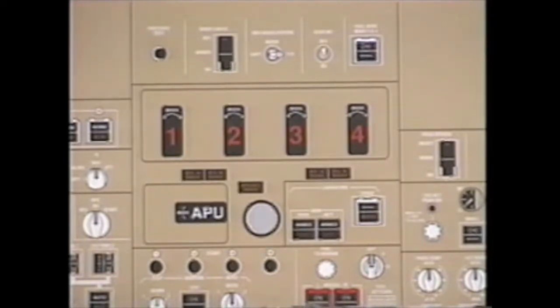This remote shutdown panel contains a stop button, a fire control handle, a continuous horn, and a red light. The horn will sound continuous and the light will illuminate during an APU fire warning and an APU fire test. If the APU is running and it catches fire, it should shut down automatically. It cannot fire the bottle automatically. If the APU is running and the captain does the fire overheat test, it will activate the continuous horn and illuminate the red light. However, it should not shut down the APU.